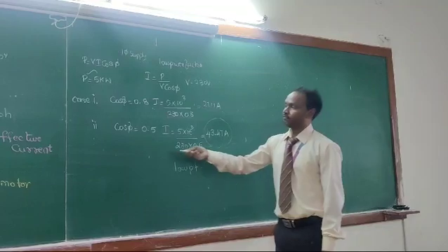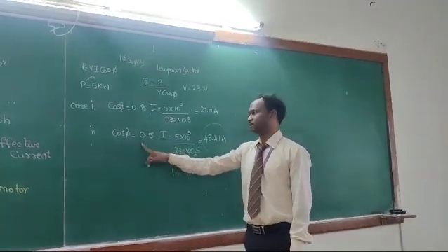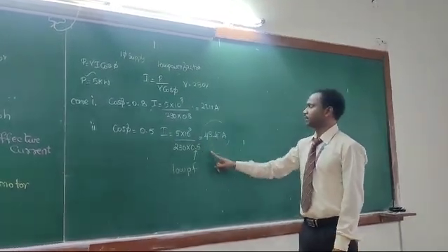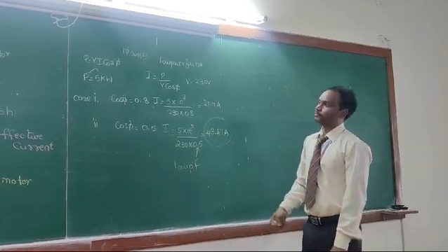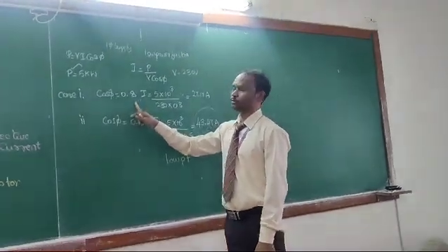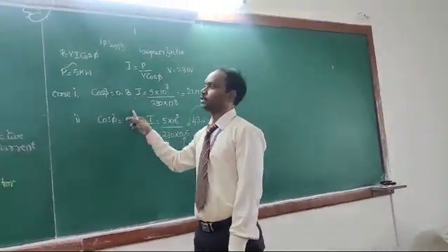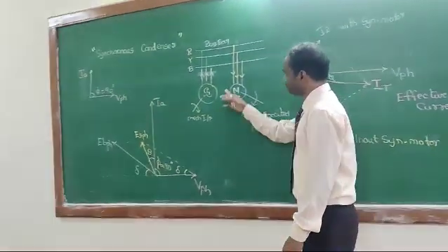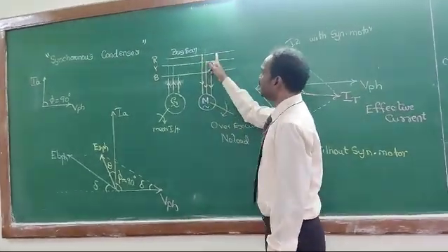So if you operate the machine at a lower power factor, more current will be consumed. This shows that we should maintain a higher power factor.